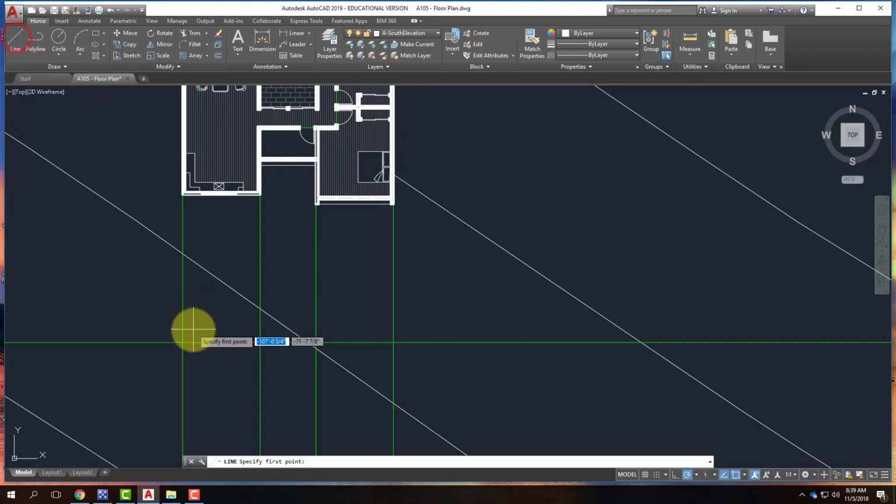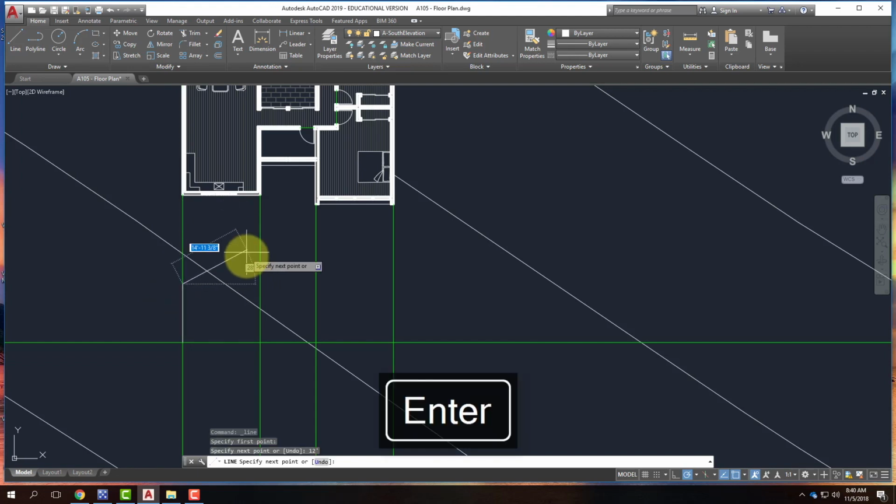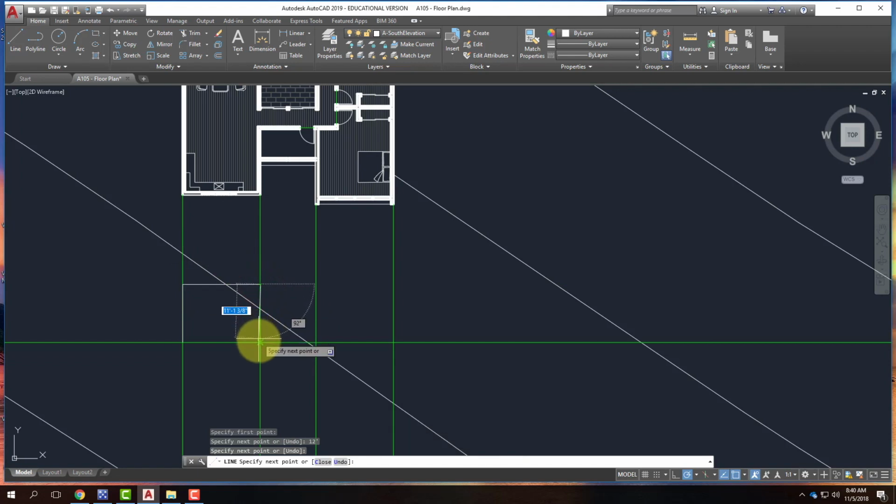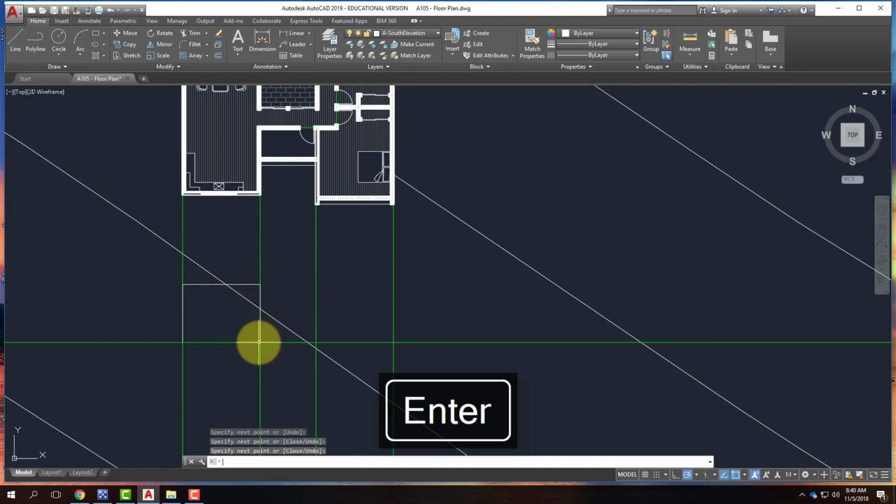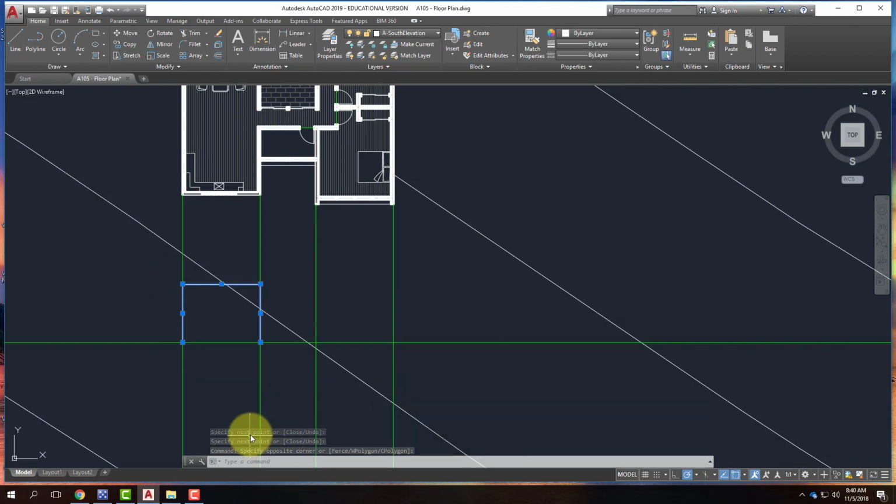And I will start right at the base there, and I will draw up however tall my first wall is going to be. So in my case, on this side, it's going to be 12 feet. So I'll draw 12 feet up, and I'll come over, and I'll draw 12 feet down, like that. So these lines that are selected right there then represent the first kind of box of my building. That's one piece of my building.